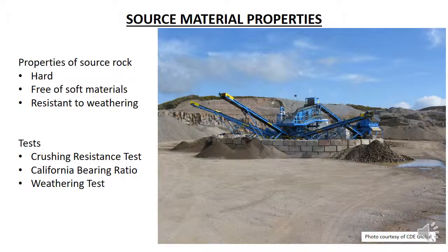This photo shows an overseas quarry. You can see the quarry face in the background, where the rock is removed from. In the foreground is a machine which crushes the rock and sorts it according to different sizes by screening. The different sizes are then mixed to form the base course aggregate.